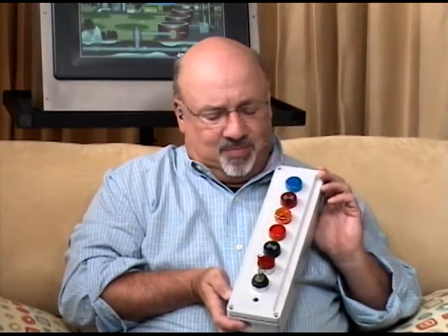What's cool about all of these, let me grab a few of them here on the counter, is you've got a couple different terminal blocks. You've got a red and a green, depending on if you want normally open or normally closed. As you can see, I've got one here in my hand that has multiple terminal blocks. It's got 4, alternating normally open, normally closed. You can stack 3 deep, so you can do 6 terminal blocks on a push button or switch.